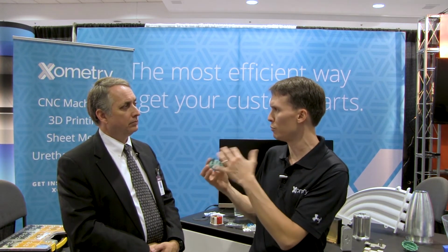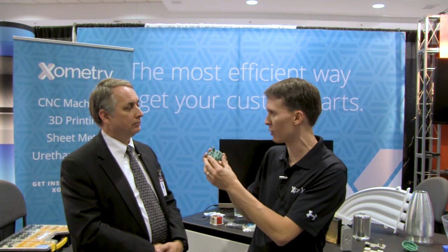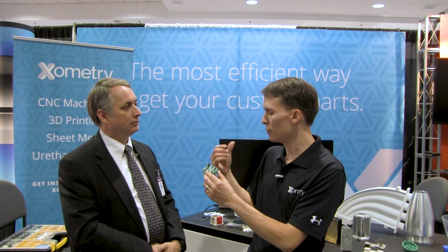And we're always expanding our platform, looking at new technologies, and even more scalable technologies like injection mold, for example. But say you're looking at something in the quantity 20 to 50 range, you may ask yourself, does this make sense for me to move to urethane casting, which is an extremely robust end-use manufacturing process that's kind of a subsidiary of 3D printing, where you're using a master pattern, making a mold, and then injecting urethane to create your parts out of it. But you also may be able to go direct to a digital manufacturing process like 3D printing.